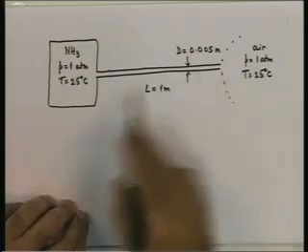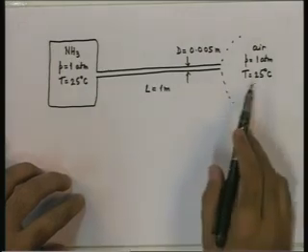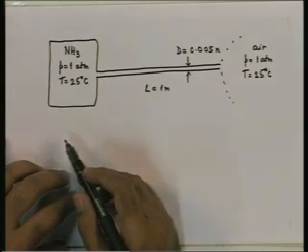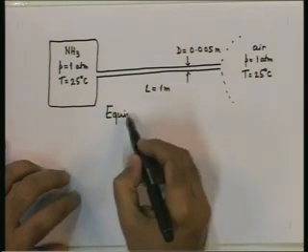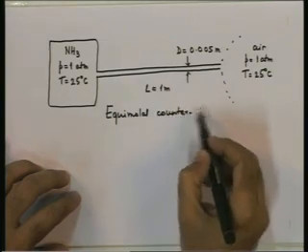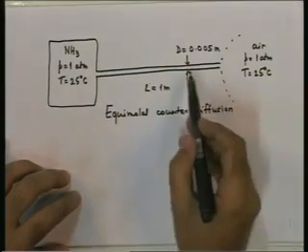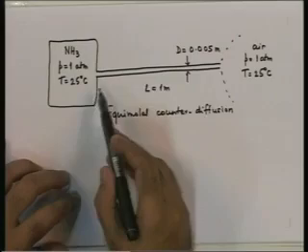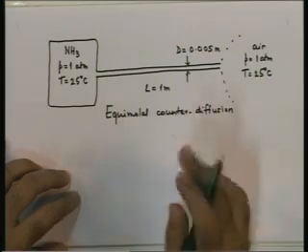Because the pressures are the same, the temperatures are the same, if we assume air as well as the ammonia vapor to behave like ideal gases, this is a case of equimolar counter diffusion. The duct is narrow and long, so we will assume a one dimensional situation, and we will also assume that a steady state exists.